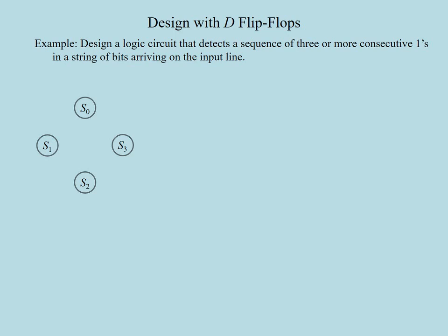If the system is in a 0 state, that is, if the last bit has been a 0, a transition will be made to S1 as soon as a 1 is received. If the next bit is also 1, the circuit will be in S2. In these cases, the output is 0. Whenever the third consecutive 1 arrives, the system goes to the state S3, while it will switch its output to 1 in doing so. It will be staying in S3 as long as the arriving bits are 1.